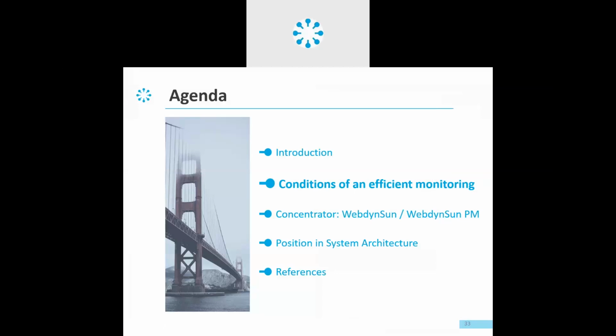After discussing all these things, I have the flexibility to share report by SMS text. Data loggers have the possibility of SMS, but SMS are meant for diagnostic purposes. When there is no internet connectivity and nobody is available on the site, but we still need to check whether the data logger is alive or the site is functioning, we can send some SMS commands with some specific notations, and we can get the particular answer from the data logger itself. But it will not give you the data specifically through SMS, or the alerts through SMS at the data logger level.